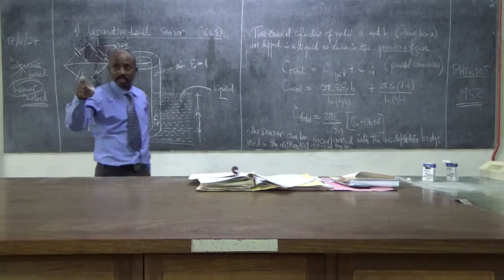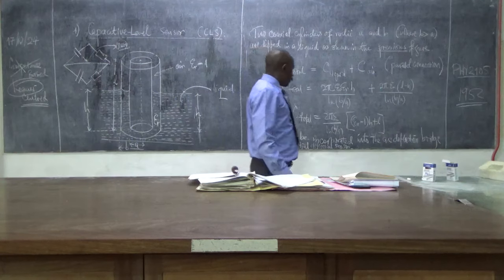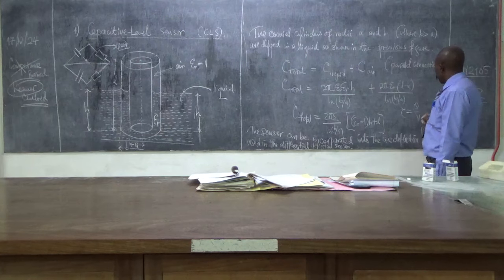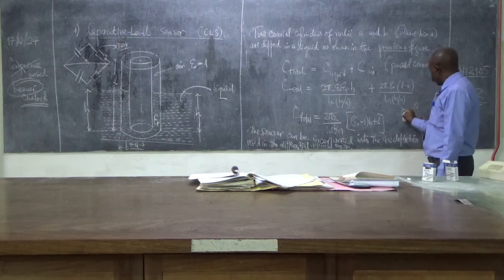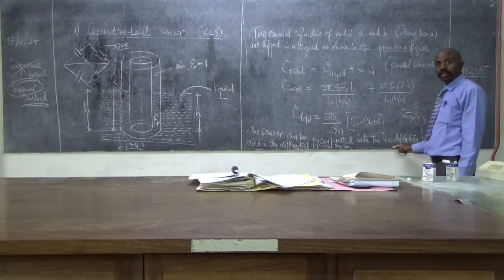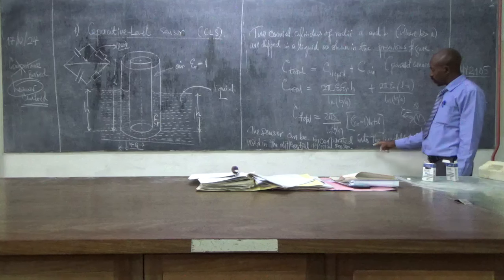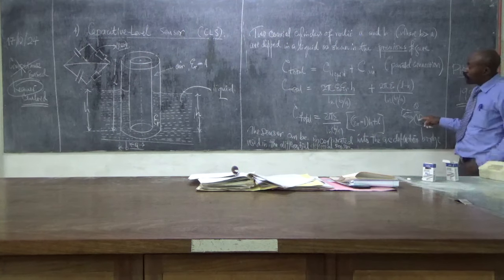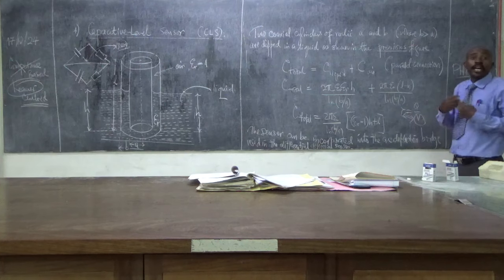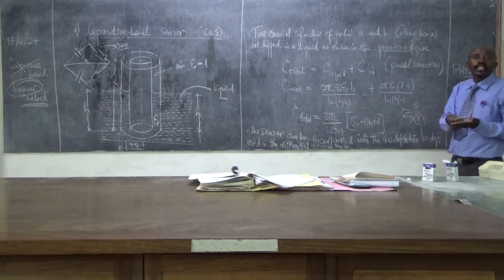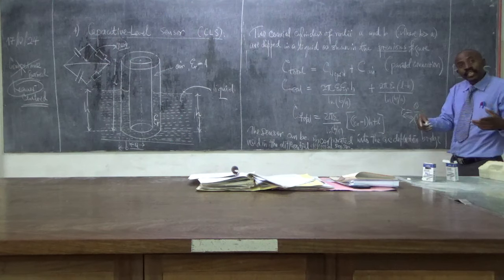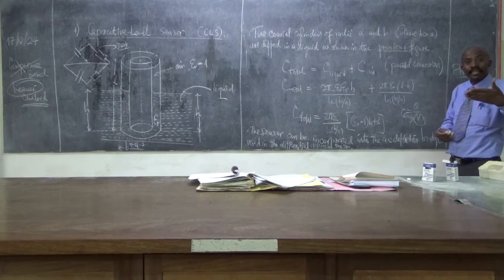So the statement I was saying is that because we know C is equal to Q over V, we can correlate this C to V by integrating it in the AC deflection bridge, and then this capacitance can be read as a voltage. The change in the capacitance is read as a voltage, which is displayed on our 7-segment display.